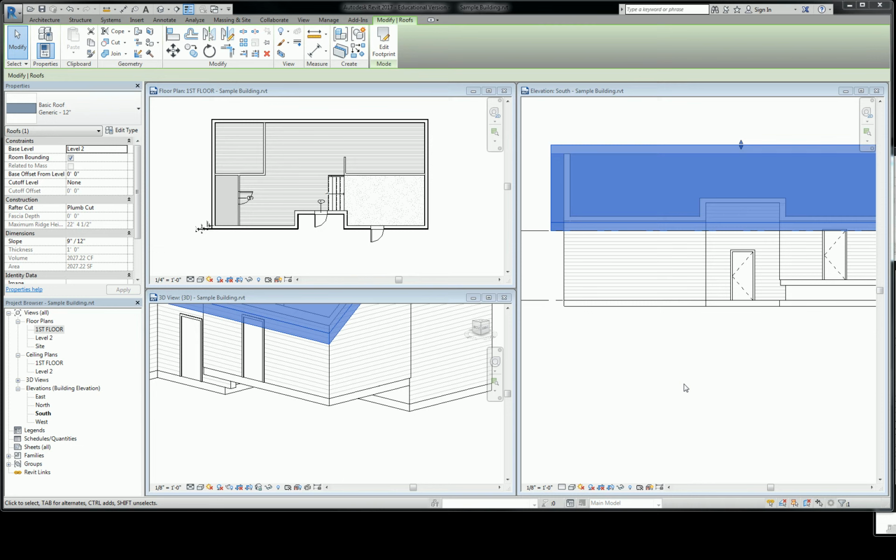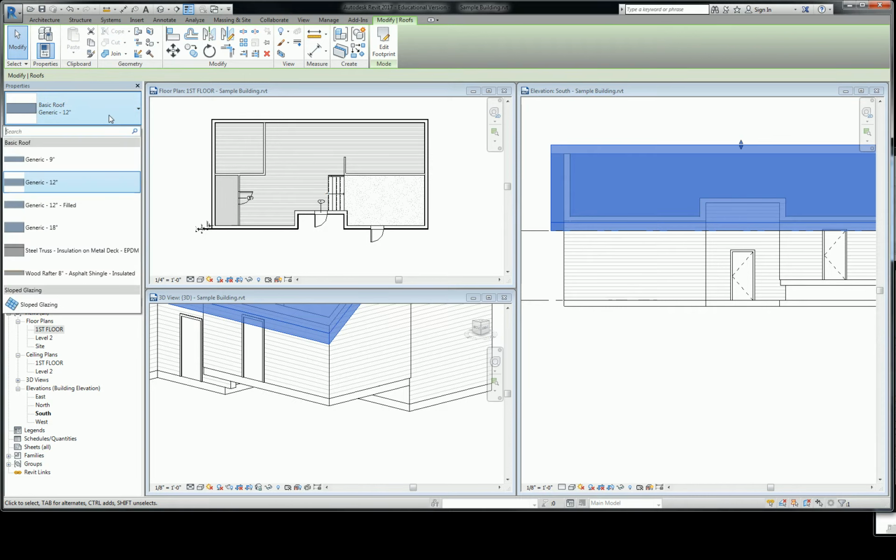All right, next up, we're going to look at the roof assembly. Again, this one's going to kind of blast right by because you've already seen it, and there might already be an assembly for it, right? So this is a wood frame structure. The roof assembly is going to be made out of joists and plywood, just like the floor. In fact, when you're looking at fire rating details, they treat floors and roofs almost exactly the same because they have a lot of the same physical and fire resistant properties.